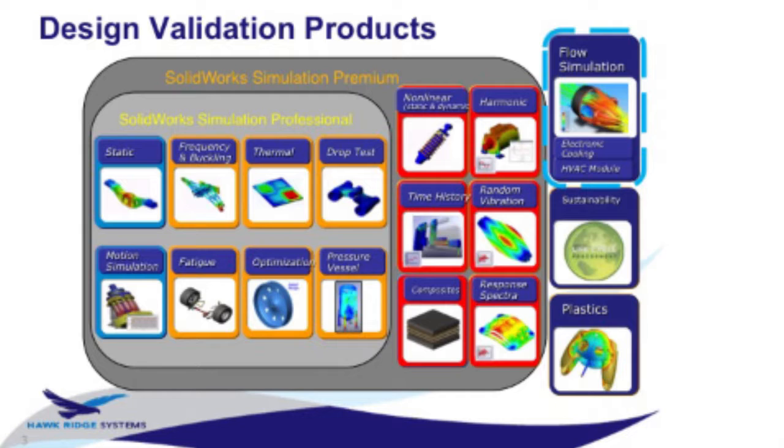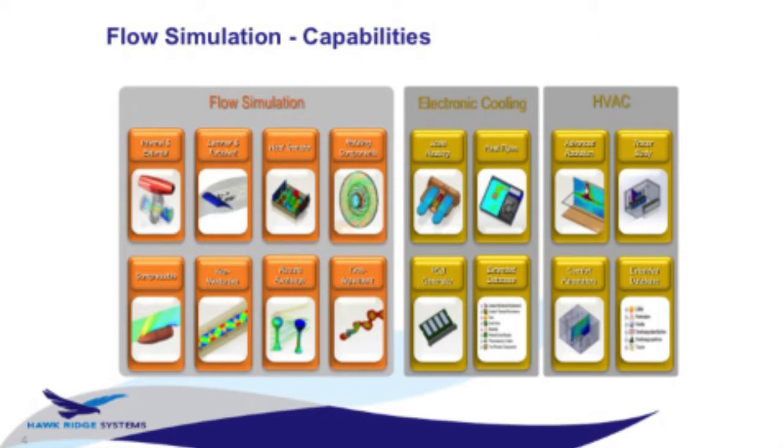Stemming a little bit further, with flow simulation what we can do is basic internal and external flow, seeing what's going on within your bodies and your electronic enclosures, or we can do aerodynamic design. Say you're modeling a car, we can model the fluid surrounding that body. It's also a great tool for heat transfer problems, thermal fluid analysis, where we can account for the fluid, the heat rising, natural convection coming out of these bodies, and really get good results for your heat transfer problem.